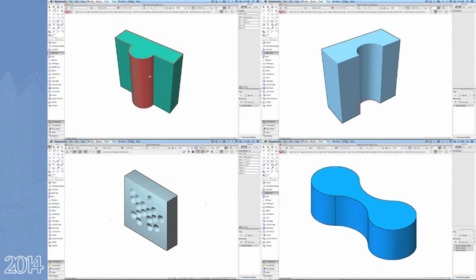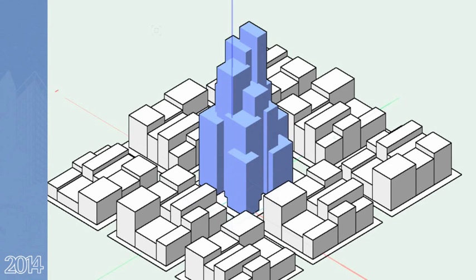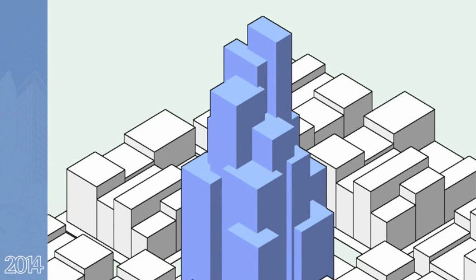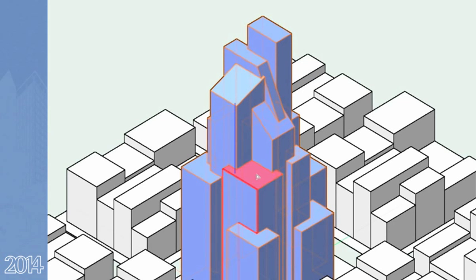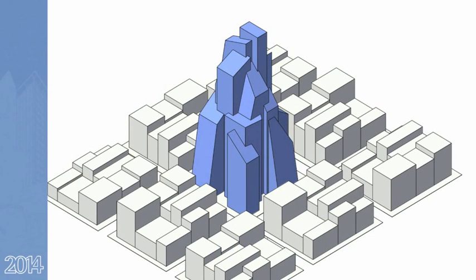Taper Face can be used to widen the base of solids and make tops narrow, and lets you get very creative when modifying solid subtractions. In its simplest form, the tool will help you explore new design ideas by deforming solid objects. Let's take a look at this massing model and explore some design alternatives. With the Tangent Faces mode, you can quickly and directly pitch all the rooftops and explore different design alternatives for this building, something not easily accomplished previously.